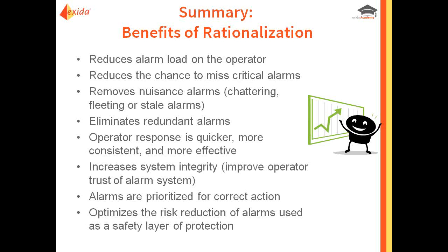We've prioritized the alarms following a repeatable methodology that's derived from a priority matrix that relates to business risk factors and business financial impact considerations. We've also talked about optimizing the operator's response and the fact that performing alarm rationalization, if you're going to use alarms as a layer of protection, is a very important thing to do to eliminate all the other alarms that get in the way of the operator responding appropriately, and then to make sure that the alarm which is being used as the layer of protection is designed appropriately.